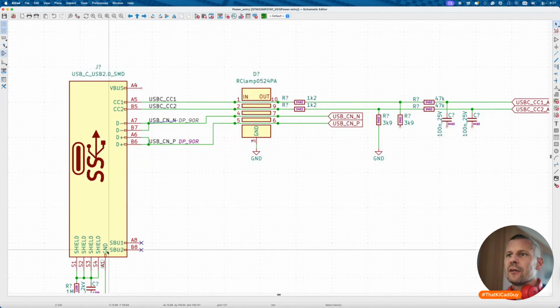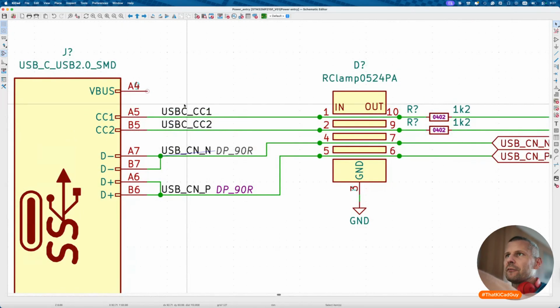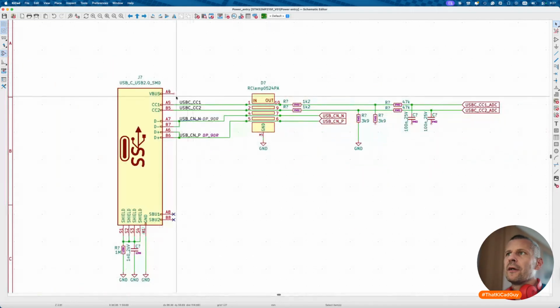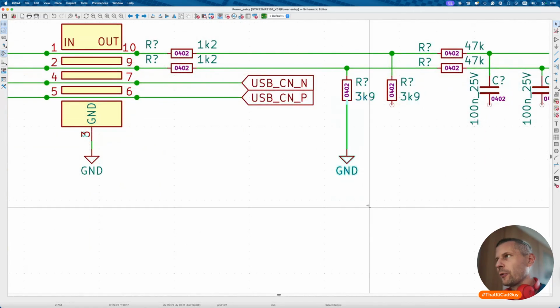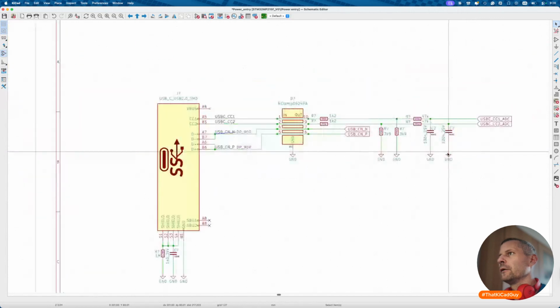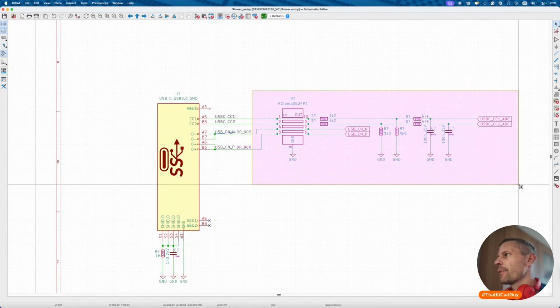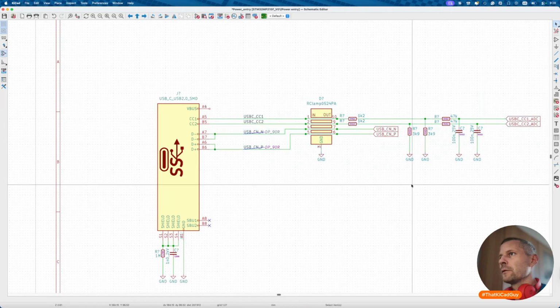So if it's active, you can see that all the stacked ground signals are here visible, or for instance here. It reminds me that we need to route the VBus with the SD connection on it. So yeah, just a side note. And it means that I have to finish this grounding and work on the ESD protection of the VBus. So I will create more space.